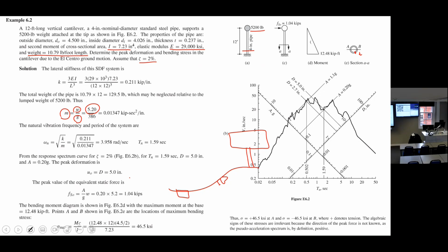And from this module, if you remember, we had several examples in the past lectures that for a very simple cantilever, if this is P, delta will be PL^3 over 3EI, which means P is 3EI over L^3 times delta, which means this is K. This is the stiffness.